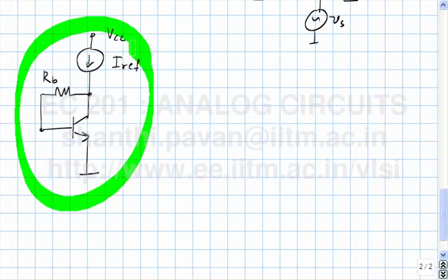In an NMOS transistor, the drain can go one threshold voltage below the gate and the transistor will still be in the saturation region where it gives you gain. In the bipolar transistor,